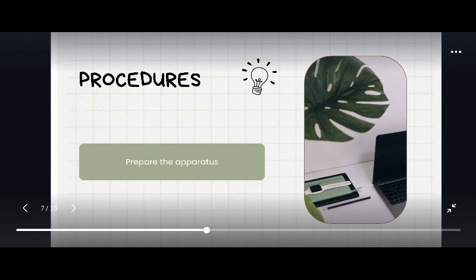Record the mass M2. Pour about 10 milliliter de-aired distilled water in the bottle to soak the soil. Leave it for a period of 2 to 10 hours. Then, pour some more distilled water to make the bottle half full. Remove the entrapped air by applying partial vacuum. Pour some more distilled water into the bottle and fill it completely without any entrapped bubble. Put the stopper on. Keep the bottle on the stand in constant temperature water bath for 1 hour.